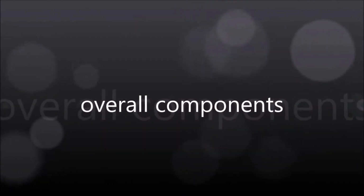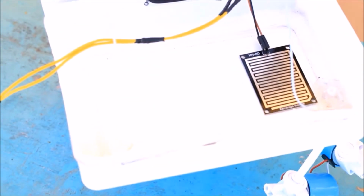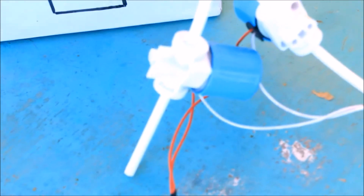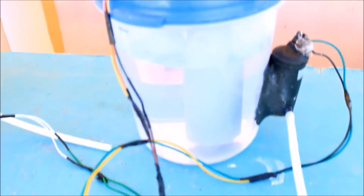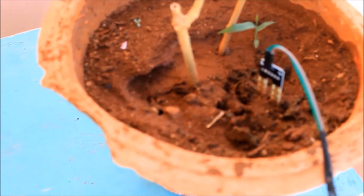The overall components used in this project: the LPC2148 microcontroller kit, the rain sensor placed on the terrace, and 2 solenoid valves, one is led to air and the other one is led to the sump, which is used to fill the sump. The tank or sump consists of two components: an IR sensor as a level sensor, which is placed on the top, and the pump. Finally, the soil moisture sensor, which is placed in the garden area.